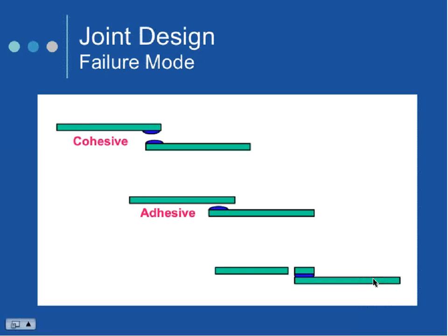If you see all of a sudden the adhesive is sticking to one substrate, but it's not sticking to the other, that's going to lead us down a path of investigation that's very different than either of the other scenarios, right? What are some of the things you might consider if all of a sudden this happened and you'd had excellent adhesion to both substrates in the past? Contamination. Contamination. That's the first place I'm going to go.